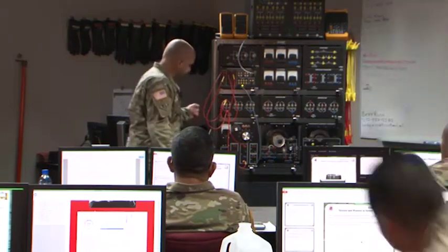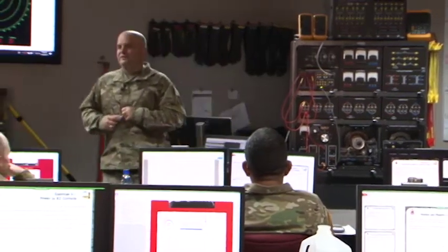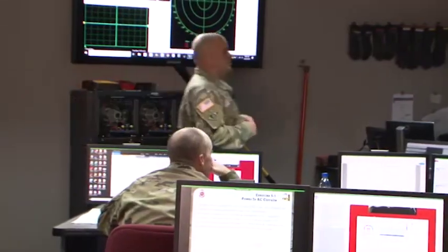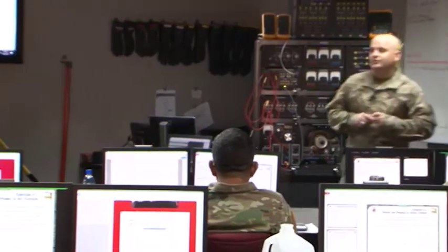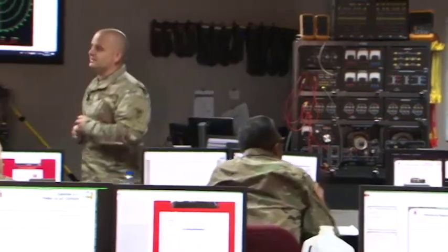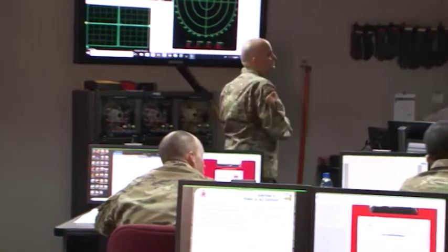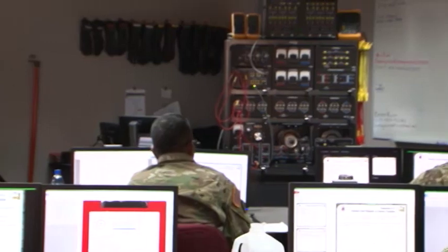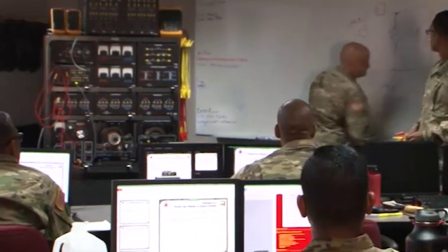Yep, good. Okay. So let's talk about what we should expect. All right. Well, if I have a purely resistive circuit, right, and I have 124.8 volts, and I've got 171 ohms of load, what should be my current going through the circuit? Calculators, when I say what should be the current, that's indicative of you grab your calculators and calculate it out, please. 0.73?